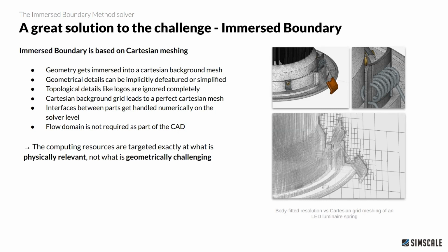So that's great. And as the geometry is just embedded and not completely resolved, the interfaces between, for example, the solids and the fluid region, or solids and solids, they are rather treated now numerically on the solver level. So there it is taken care of that the heat transfer between parts, or the convective heat transfer from the solid parts to the fluid, is taken into account based on the resolution that was applied around these surfaces, and that this is correctly taken care of, instead of doing this by fully resolving the geometry in the mesh.